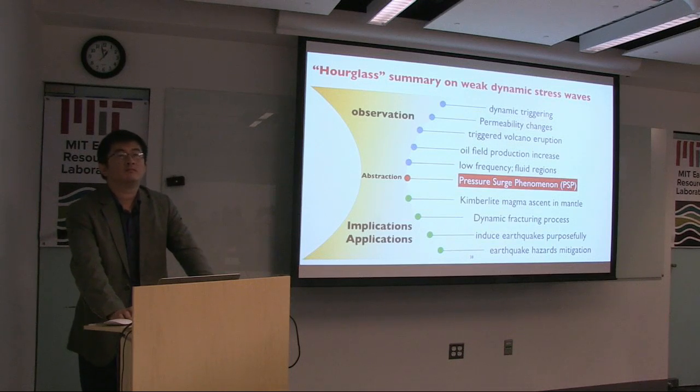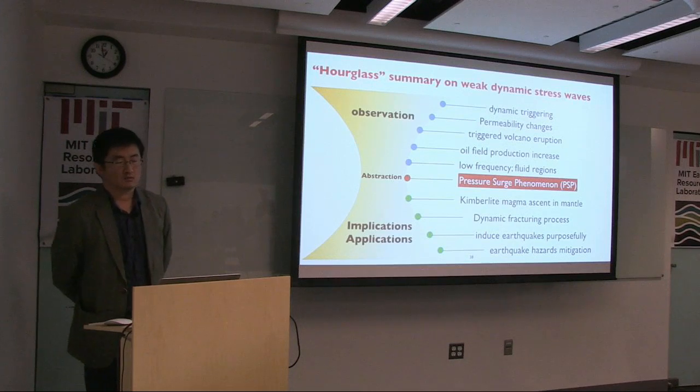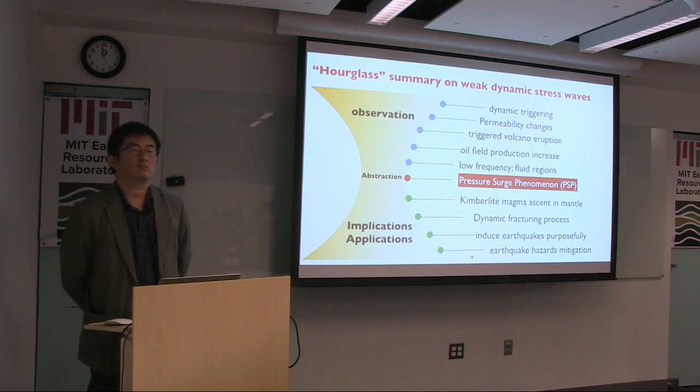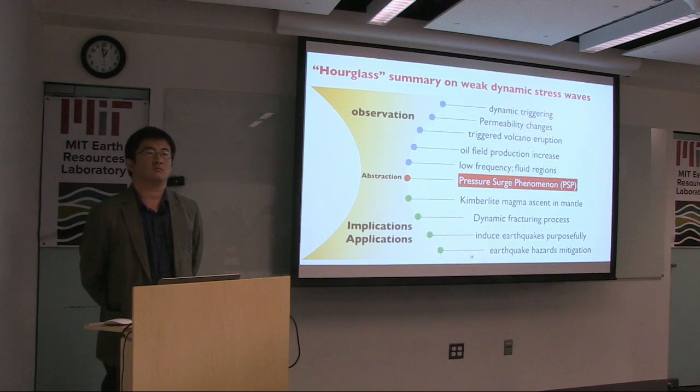So one remedy is that you either calculate the intensity factor for fracture, or, more precisely, use the generalized J integral. That is a very good way to estimate the size impact. I think your model can go in that direction.